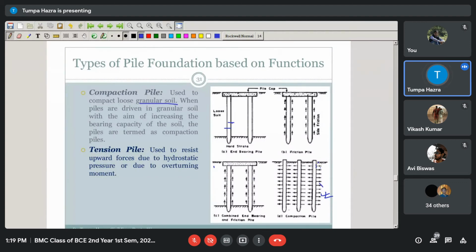So therefore the piles can be made up of weaker material like bamboo sticks, timbers, etc. Sometimes first the hole is created by some timber or bamboo stick, and then those holes are filled with dense sand.